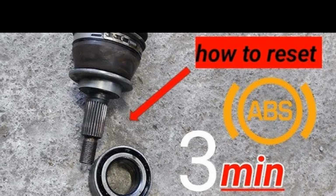4. Potential problems with integrated magnets. Magnets embedded in the bearing grease seal can sometimes cause problems. A wheel speed sensor code may be triggered, indicating a malfunction. In such cases, the bearing will need to be replaced to resolve the problem.